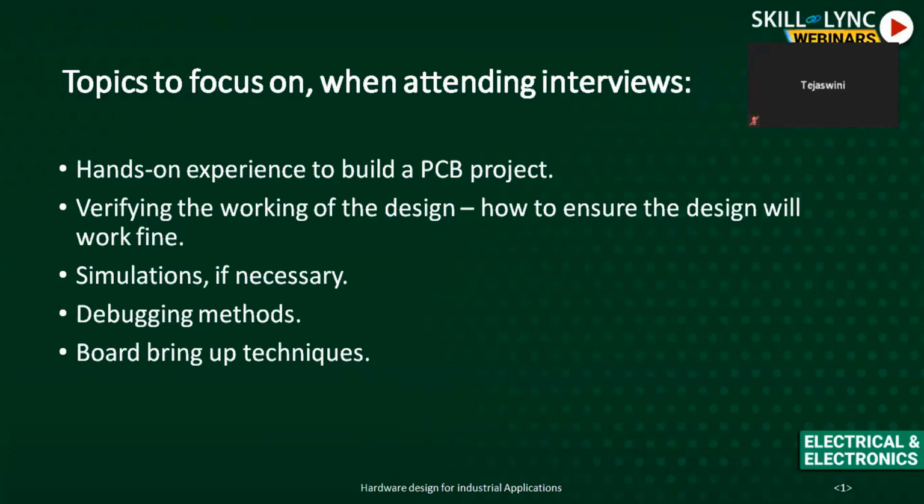How does design verification take place? How do you ensure that the design will work fine the first time? Once you plug in the power supply, it won't blast. How do you verify it? And once you connect to some external devices, the communication will work fine and everything. You should be able to know it. And then simulations, if required, like power supply simulations; most of them you can simulate without building an actual product itself.